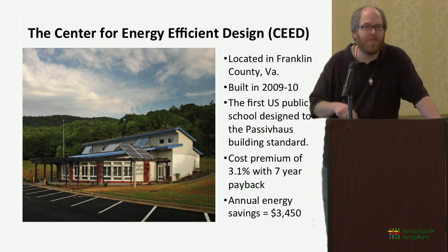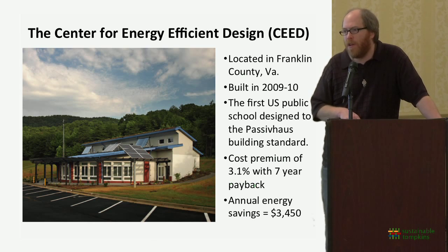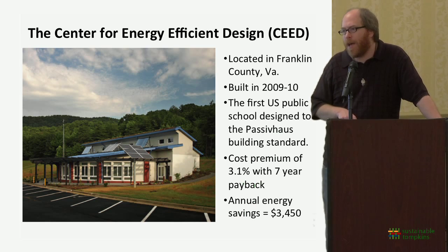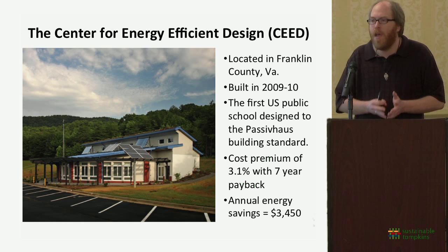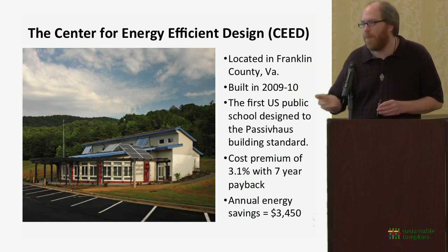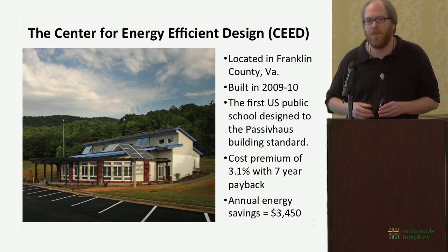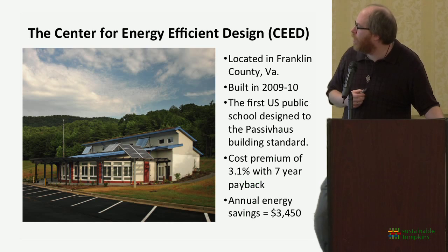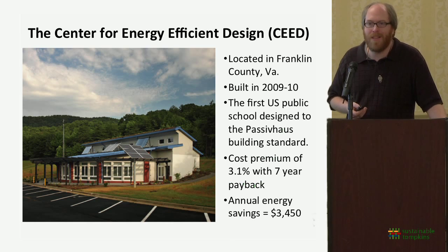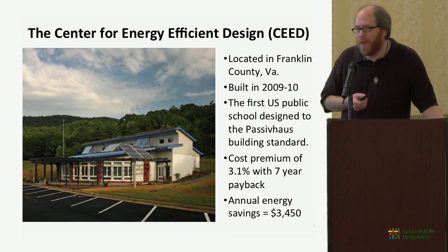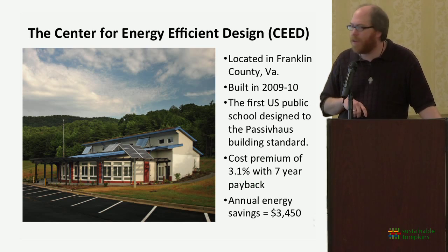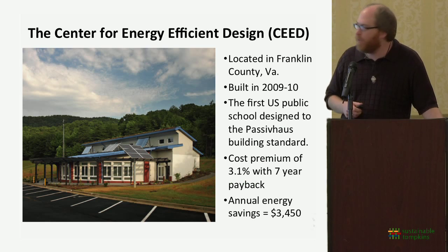So I will give you a couple of quick examples of commercial spaces that have been built to what is called Passivehaus. Passivehaus is originally a German set of building standards, and the idea behind Passivehaus is relatively simple: if you tighten the envelope enough, you actually cross over and begin to make it more economically efficient because you can undersize your mechanical systems. The more tightly you build the envelope, the more efficiently you can then build everything else. So these next few buildings, they're all built by a single company down in Virginia, just to give you a sense of what has been done and what is possible.